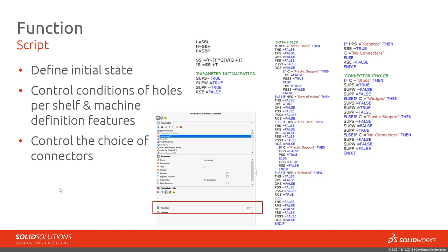Beyond that, you've got if statements, which are ultimately controlling the visibility of all of those variables as it goes through its various options. Now, having this code in play will allow the end user to define how the SWOODBox ultimately appears when moving this into a SWOOD frame.